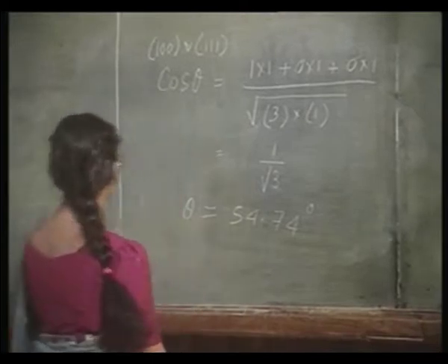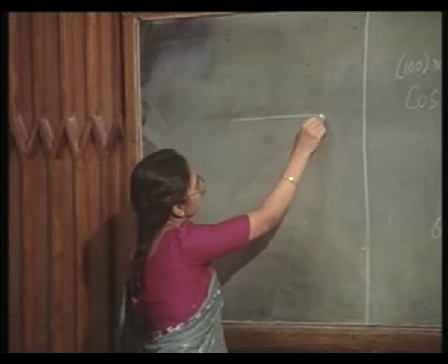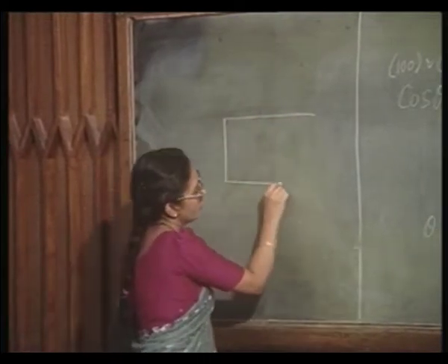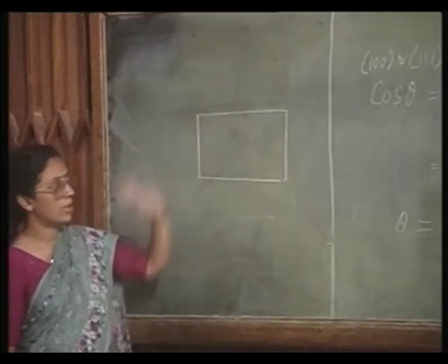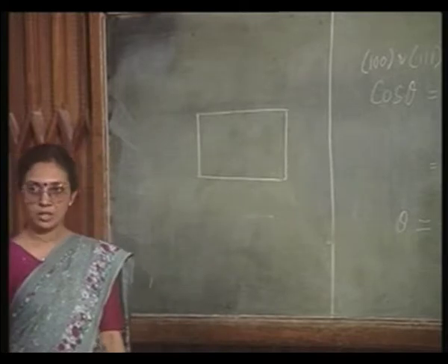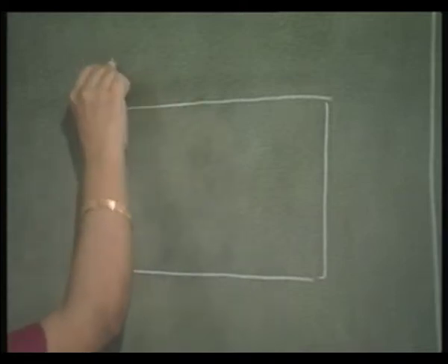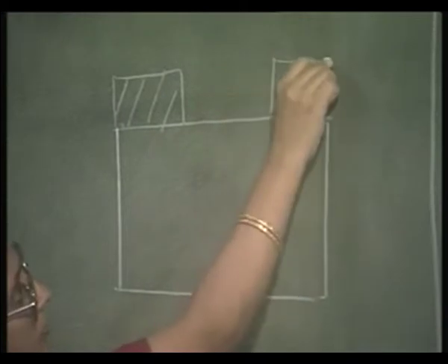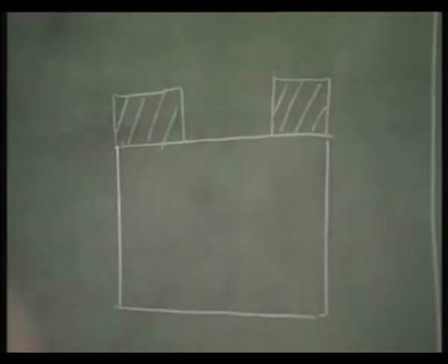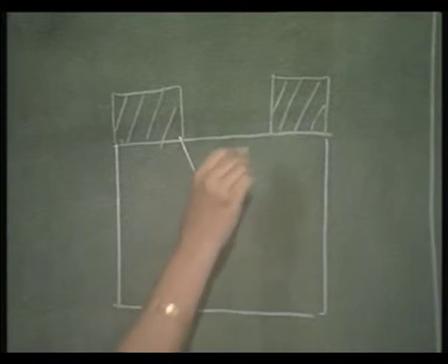What do I mean by this? What I mean is something like this. You have the 1-0-0 wafer. This is the cross sectional diagram. Now, you have exposed it to the etching through a window. Let us see, you have protected this by means of oxide, and you are subjecting it to etching. So, what is going to happen? The etching is going to proceed like this.